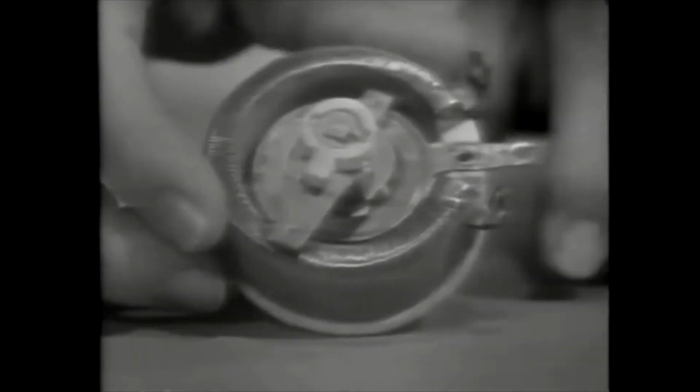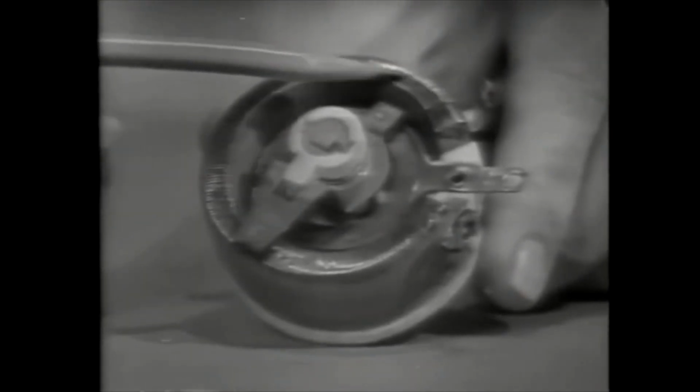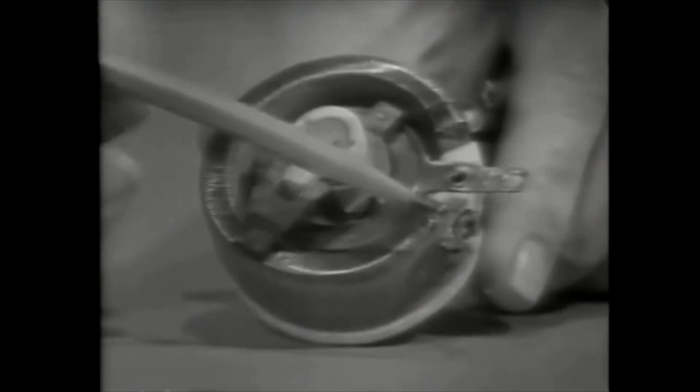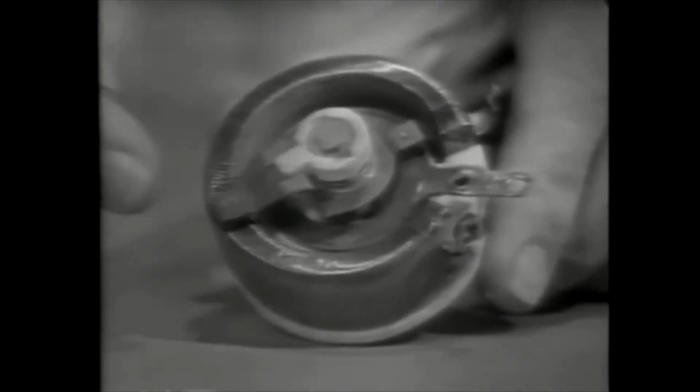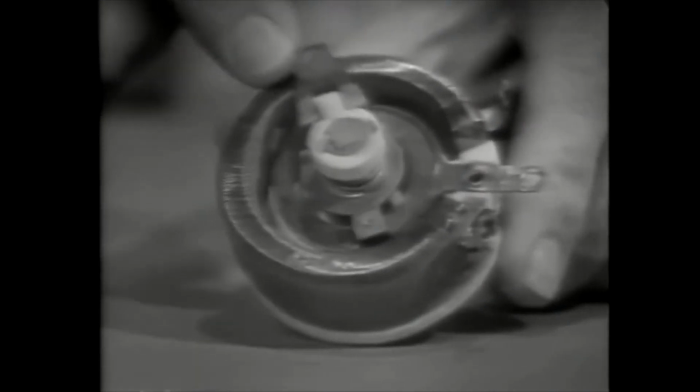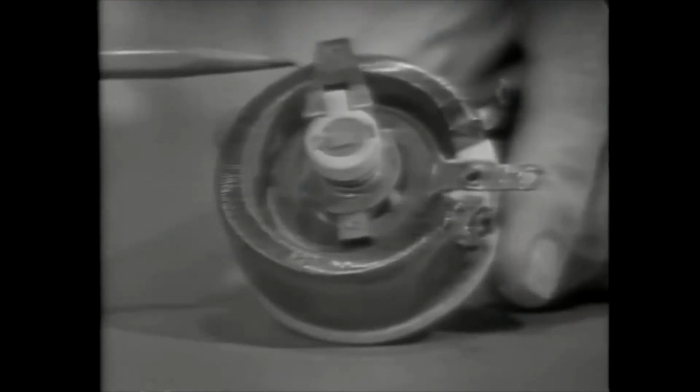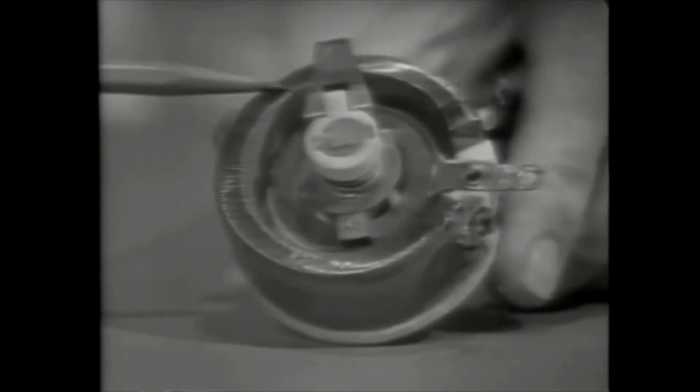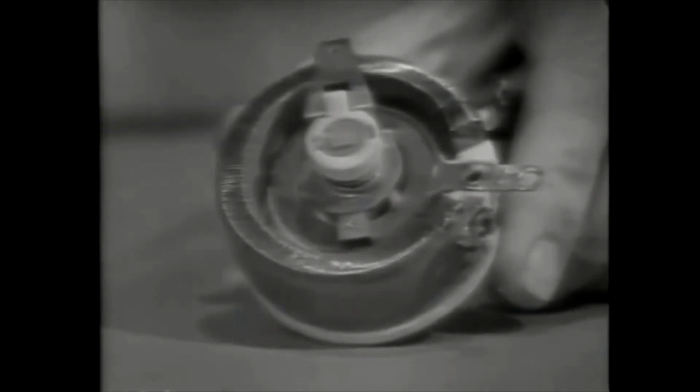Another common type of wire wound resistor is a variable wire wound resistor. Now, the wire is here in this semicircle, and it's a fixed resistance from this tap to this tap. The variable part of the resistor is provided by this contact. For example, if I move the contact to here, I've increased the length of the material that I'm using from the contact to this terminal. Therefore, I've changed the resistance. When I move the contact, I change the length of the wire, change resistance. So a variable wire wound resistor. Again, you can select several different values of resistances from one resistor.